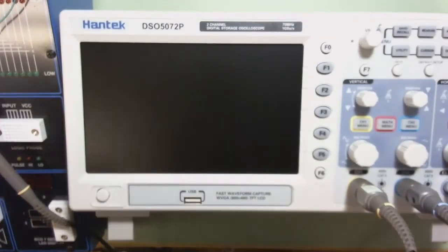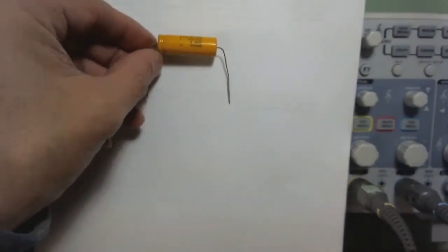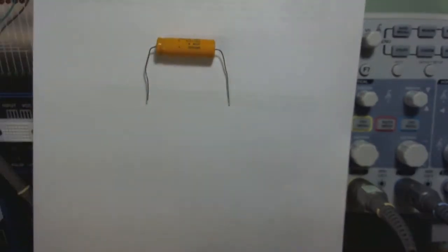Maybe I'll put this down here so we have a surface. There are lots of different types of capacitors here, and you not only need to size them by the value, so 10 microfarads or 0.1 microfarad or picofarads or nanofarads, but you also need a voltage rating to make sure you don't exceed it.